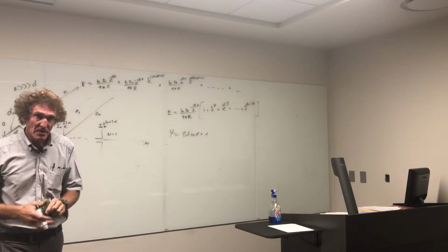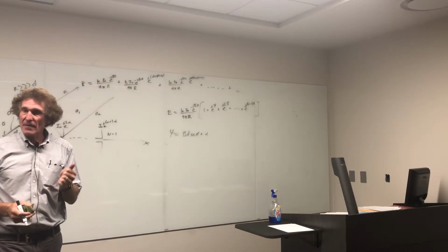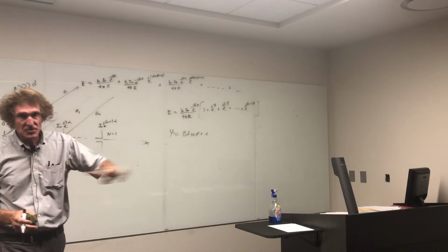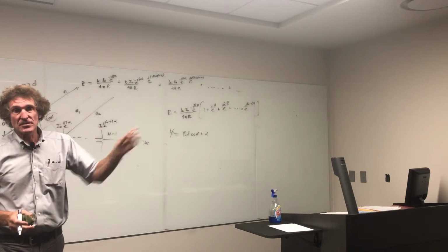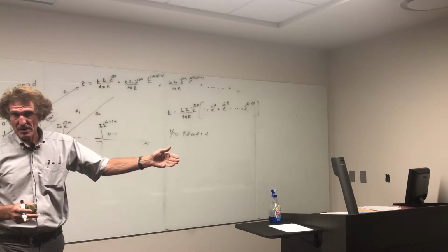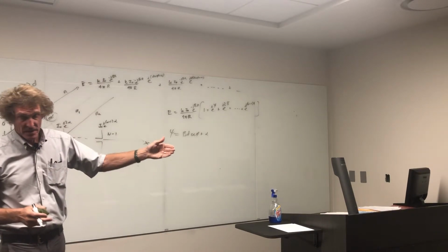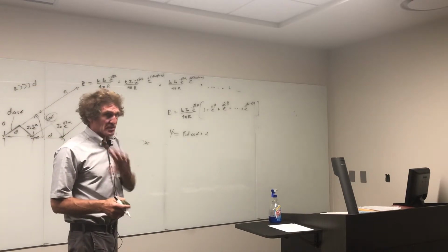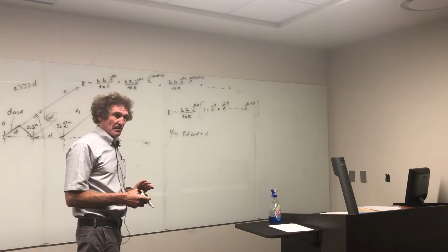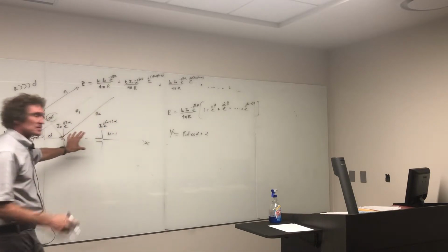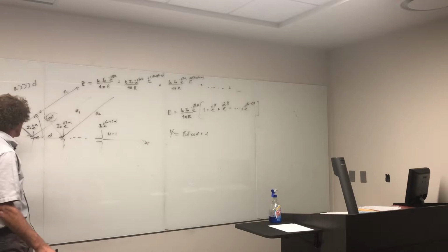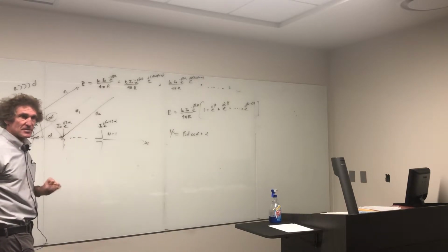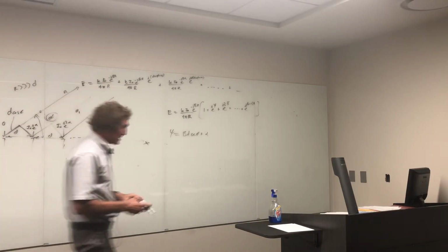Everybody got that? Now remember, I'm doing some things here that you have to realize this is what it's hinged on. The spacing is the same, they're all in a straight line, and the phase difference is progressively the same, right? So that's key. Something else about this, each one of these is radiating the same amount of power, which is a little tough to have happen all the time because the ones closer to the center have a different driving point impedance than these. So you have to have something called a power coupler. Just be aware there's more to this than meets the eye. It's not quite as simple as I'm making it.